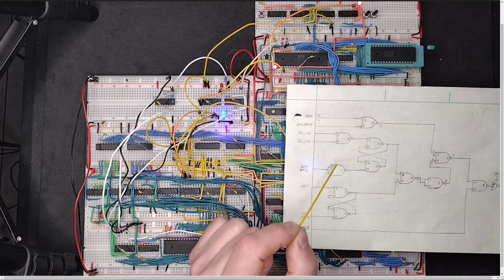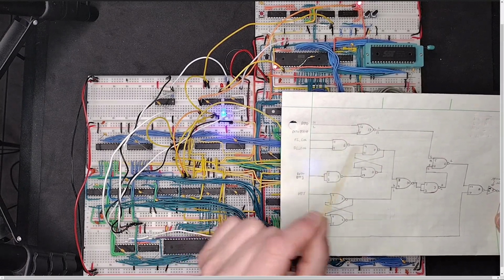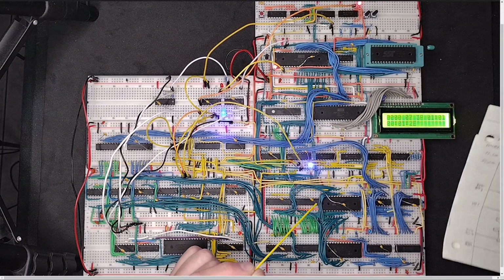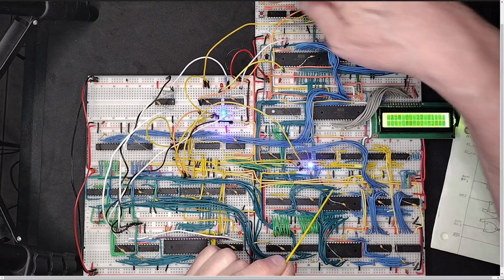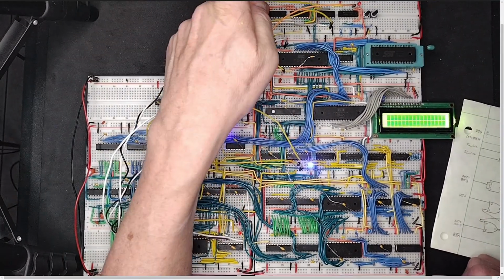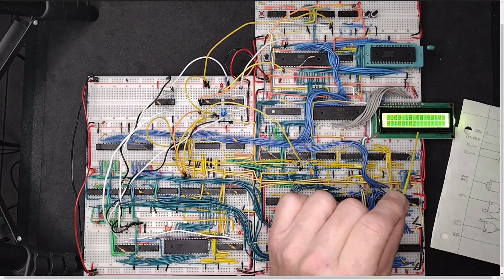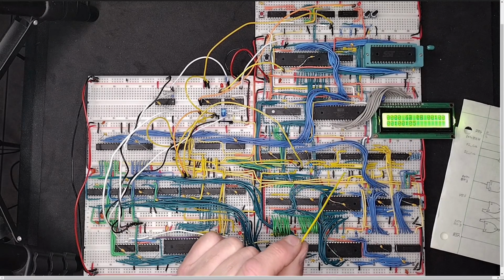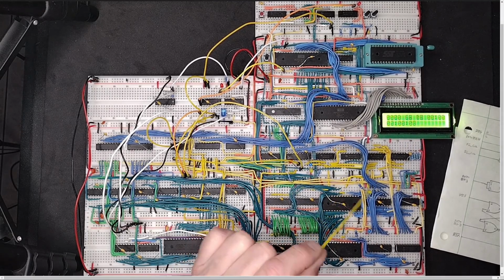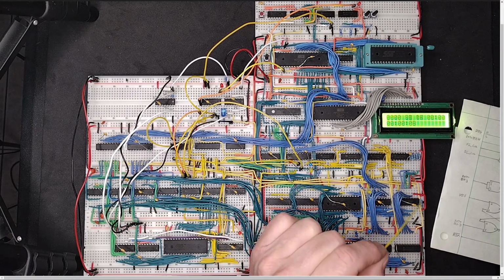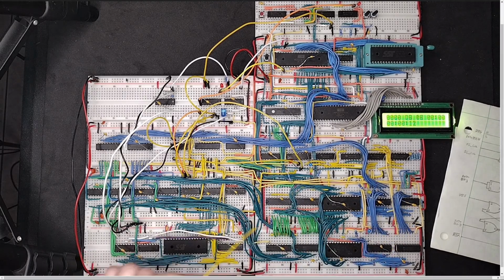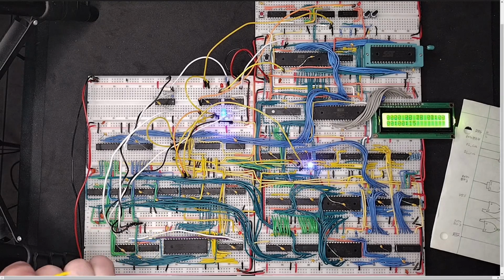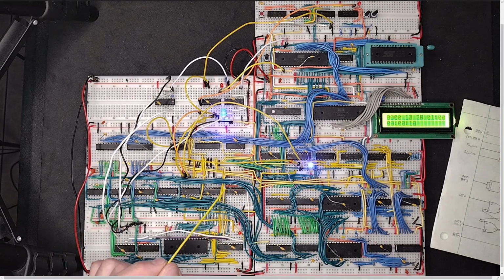This arrangement is here to detect when there is a collision between the foreground and background. And believe me, this caused quite a bit of frustration because when I'm running my memory test, let me restart that. When I'm running my memory tests, I was writing to background and foreground. The value could be anywhere from 0 to 256, which meant bit 6 in at least a quarter of the cases is going to be high in both of these, which would trigger this interrupt. So I was getting that interrupt triggered as much as 2-3 million times a second, which of course the computer couldn't keep up with handling.